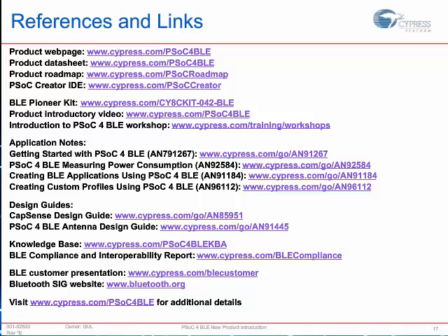This device can be configured as a peripheral, which is the most common use case for, let's say I am a fitness monitor. I'm a peripheral to a cell phone, so I'll be providing information to it. But it can also be configured as a central, where it can be listening for connections from other devices and be that host, that central host device. You can also configure it in a mode where it does a little bit of both. It switches roles between a central and a peripheral depending on what mode or situation it is in. So I guess the short answer is yes, you can absolutely implement a BLE central device with this as well.